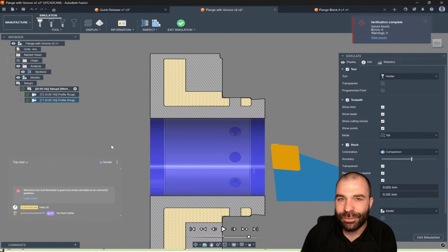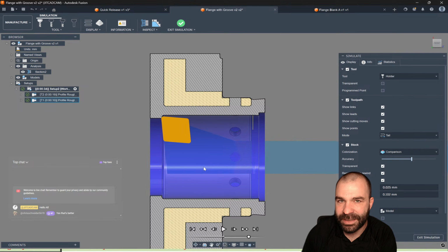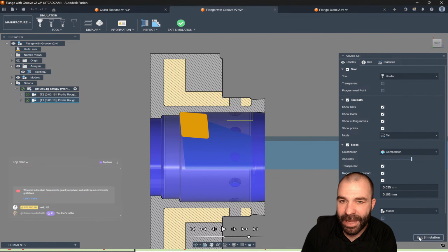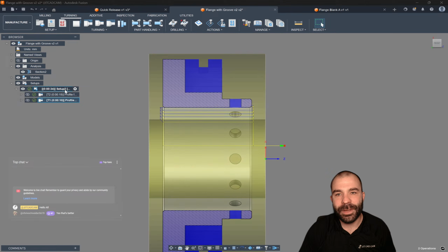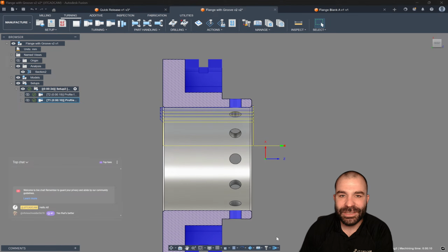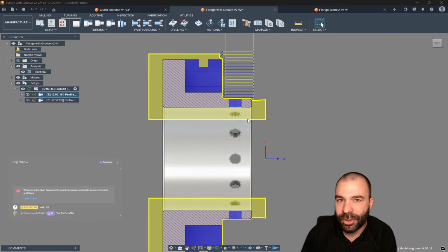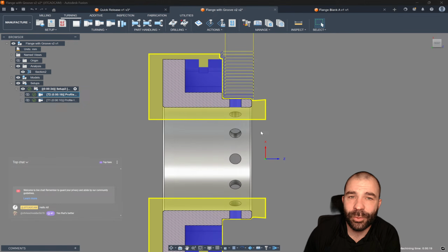Because if you notice where this tool is going to go for a safe location, as you can see, I'm hitting the backside of that tool before I get down into that cut, right? So this is something, again, the simulation is going to be your absolute best friend. And the reason for that, Hollywood magic out here, guys, is if we turn on our rest machining, and we look at our toolpath, our stock, again, my setup is going to haunt us, but I've simulated this to find out the backside of that tool is going to hit.